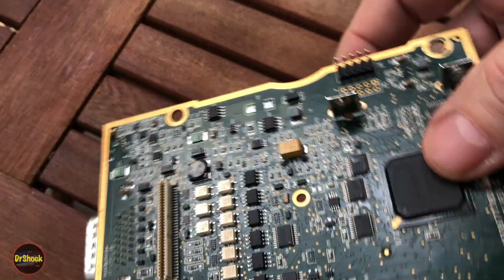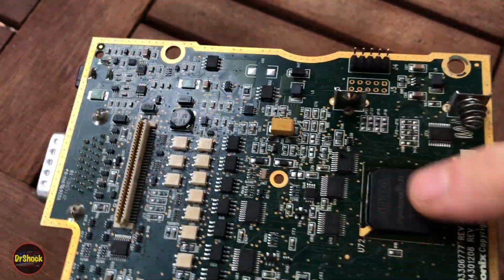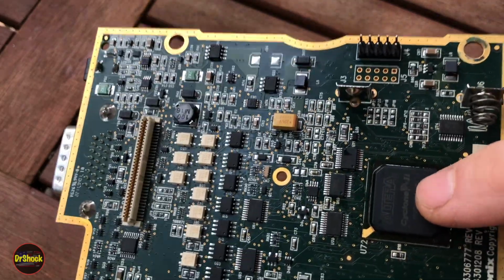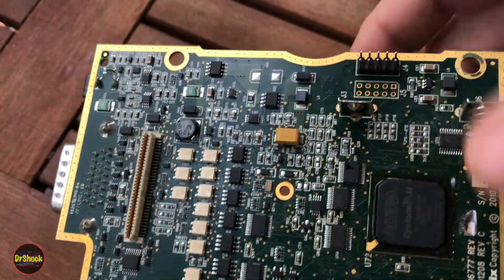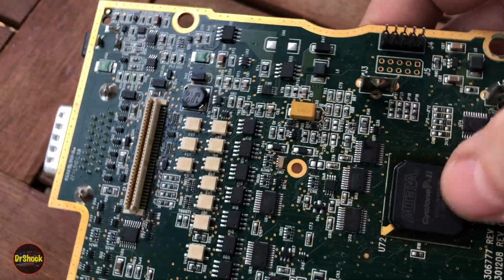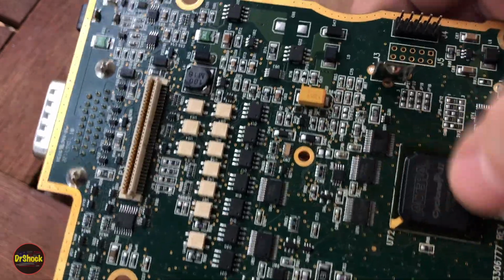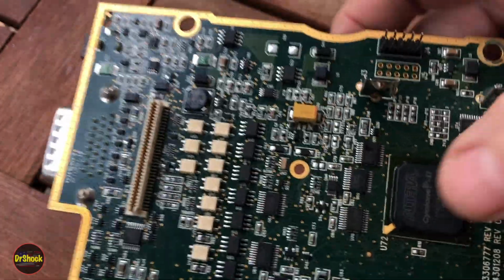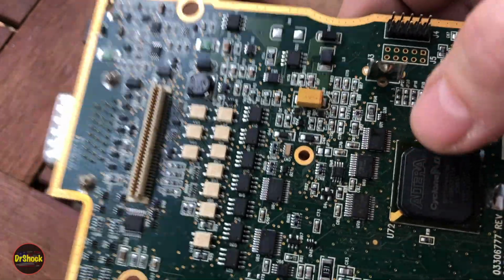So unfortunately, that makes this a bust because, like I said, it's not cost effective to reball this. It's certainly not cost effective to replace it. This particular chip runs about $100. Regardless of what you might see out there online where some Chinese sellers are trying to tell you they can sell a chip like this for $20 or $30, those are usually relabeled, not this actual part. They usually sand this off and put something else on here, and it's going to be a different speed part or something of that nature. If you're lucky, you might get a part that's been pulled and reballed, but you can't tell what you're getting there.